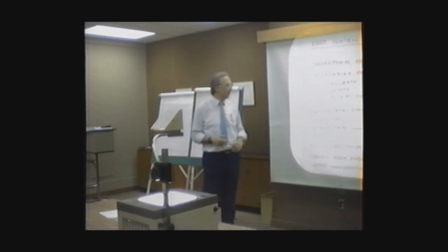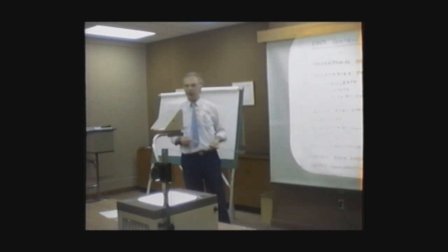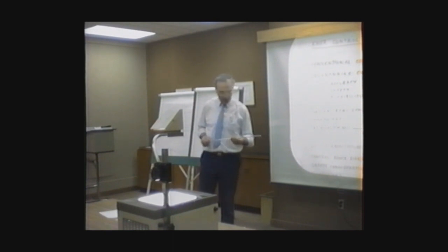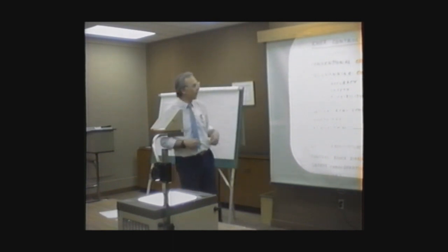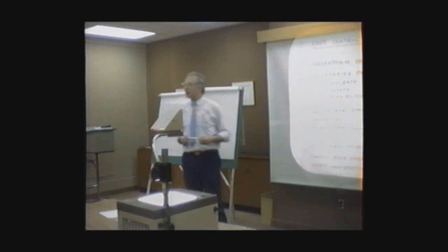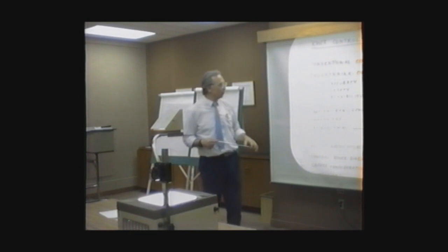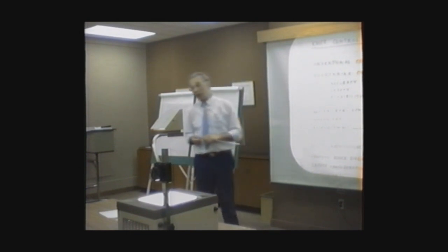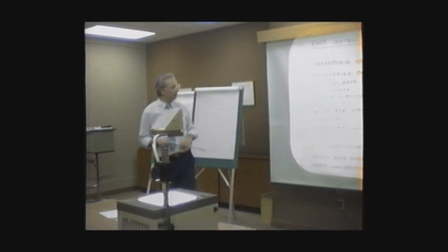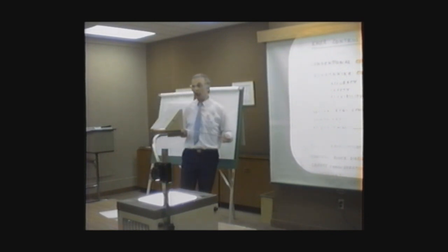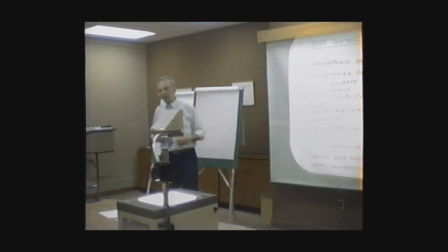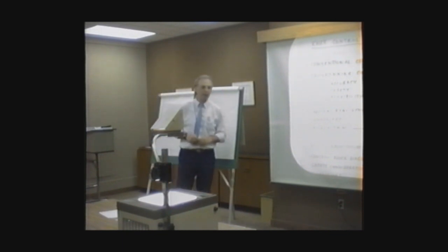That program reads the field inputs for the different thermal and neutronic variables, reads the operator input for the set point he wants to put into the reactor, then processes the inputs, taking into consideration the different safety and accuracy criteria, and finally outputs to the control rod mechanism the number of steps needed in order to maintain the set point entered by the operator.